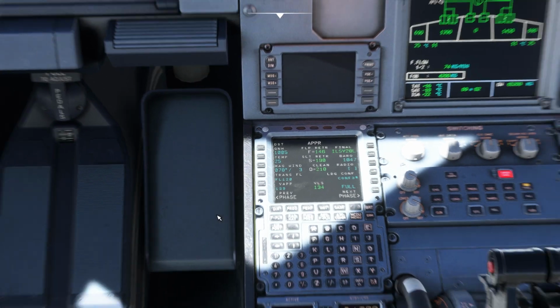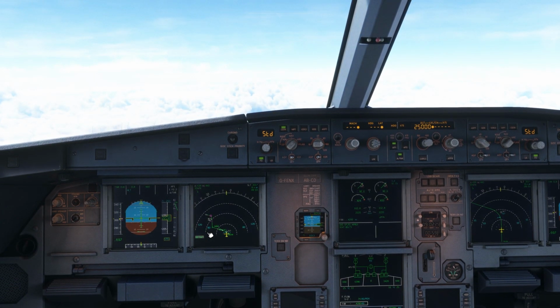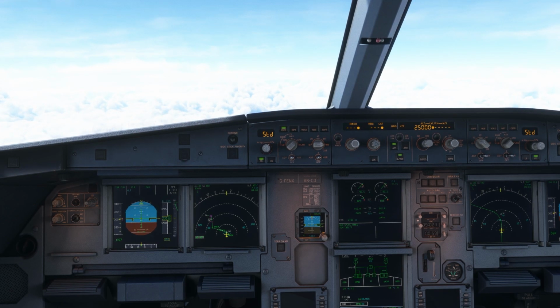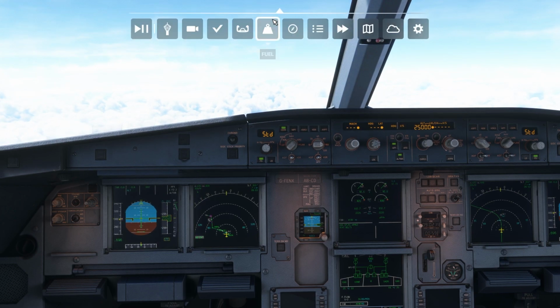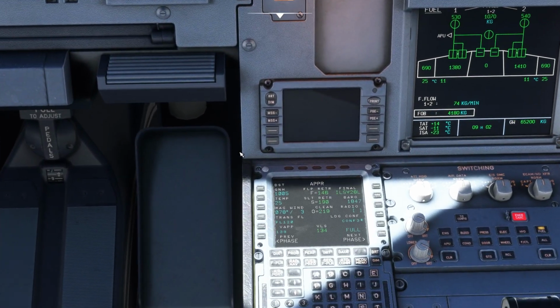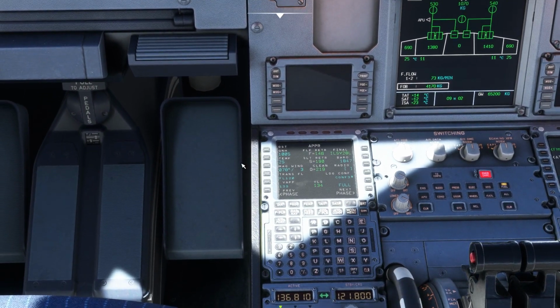Just right before the touchdown, you will hear the autopilot saying minimums. Basically, this is a decision height. If you still want to perform a go around, you can do it at that time, but after the minimums, it's difficult to perform a go around. Then you have to do a touchdown. I think it comes at 300-200 feet above the ground, depending upon different airports, but you have to enter this decision height in order to hear the autopilot saying minimums.